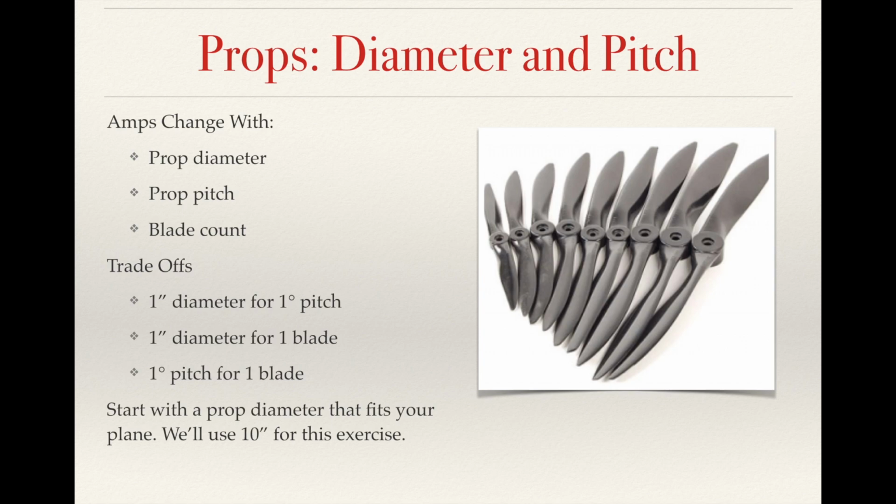So in the example we're going to use, we'll start with a prop diameter of 10 inch. We'll just say my particular airplane requires a 10-inch prop. And the idea when you're building your power system is start with a prop diameter that fits your plane.